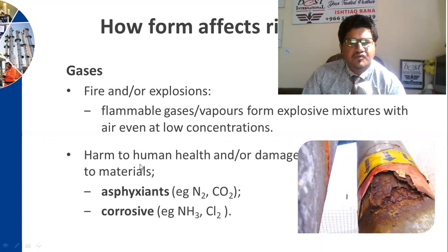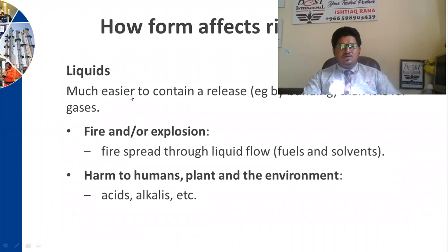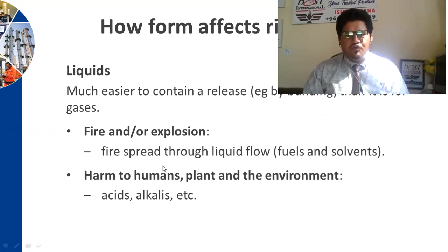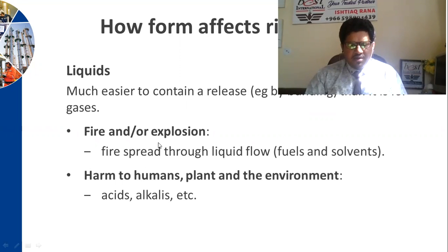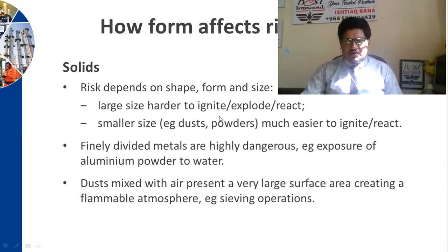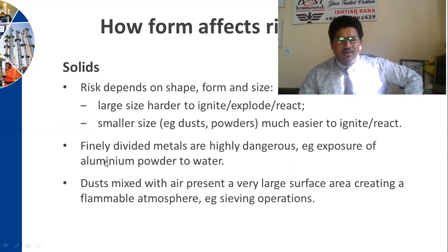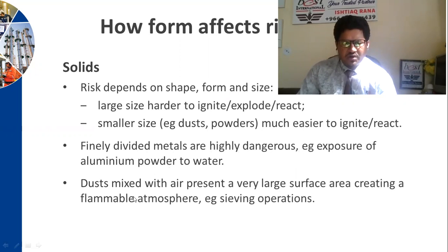Gases: fire or explosion from flammable gases, harm to human health, asphyxiation, and corrosion. Liquids are much easier to contain or release, e.g. by burning, than gases. Fire and explosion, fire spread through liquid flow, harm to humans, plant, and environment. Solids: risk depends on shape, form, and size. Large pieces are harder to ignite, explode, or react. Small sizes, such as dust and powders, are easier to ignite and react. Finally, divided metals are highly dangerous, for example aluminum powder reacting with water.